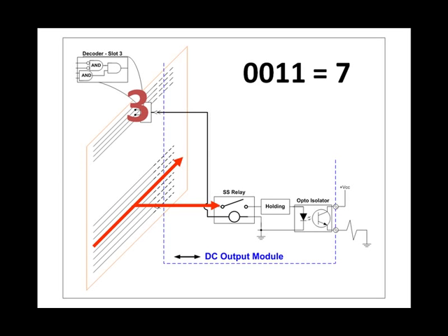So there it is, the active backplane. This is all there is to what transpires on the backplane between the I/O modules and the processor. It is, in its entirety, an array of solid-state switching designed to switch multiple I/O interfaces on and off of a common bus connected to the processor's input-output terminals. Remember, we did have input terminals and output terminals. So the 16 conductors on the back of the processor module are I/O terminals now.